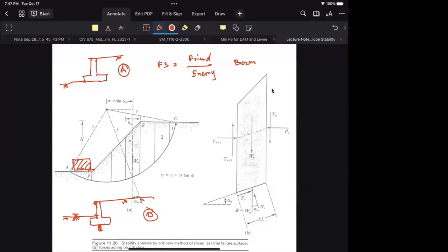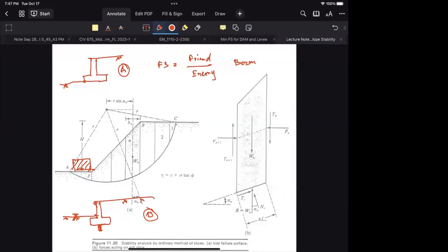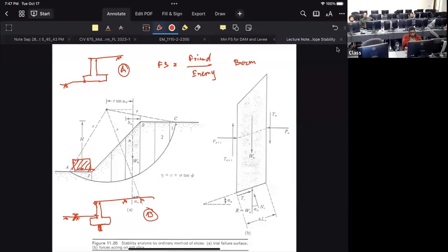Increasing the depth for the passive resistance of the soil layer. Oh, you're back. Yeah, I was here all the time, I'm just not feeling good. But when we have this key, we have more depth that we count for the passive resistance. That's the one I was looking for. Whenever you have the soil on this side, it gives you the passive resistance.